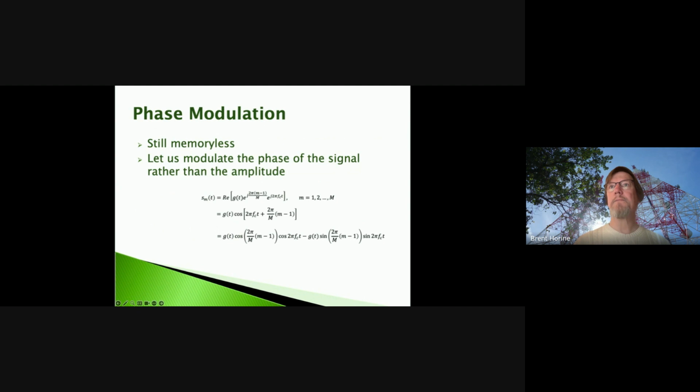But instead of just doing amplitude modulation, let's do some phase modulation, right? So we talked about how we can manipulate the amplitude, the frequency, or the phase of a signal. So let's look at this approach where we have this low pass equivalent circuit, where we can extract out the actual RF waveform by multiplying by the carrier, e to the j 2 pi f_c t.